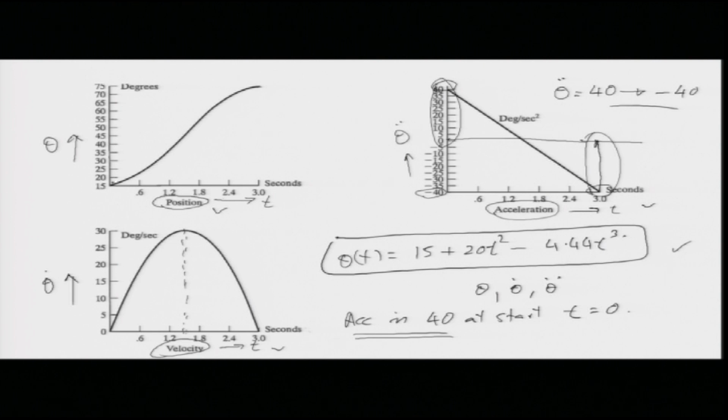Let us say that we start slowly. So, my joint is here, it is going to go to this point. What we are doing is, we are going to start very slowly, then we will have linear motion, then we will stop very slowly. So, we call it a linear function with parabolic blends.